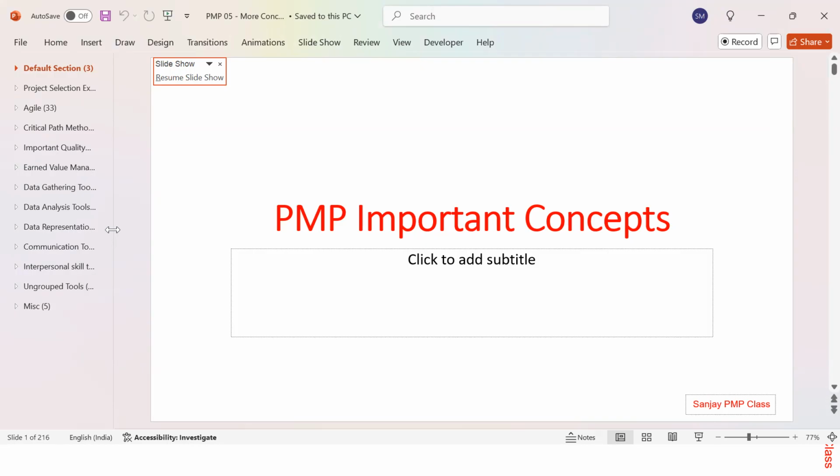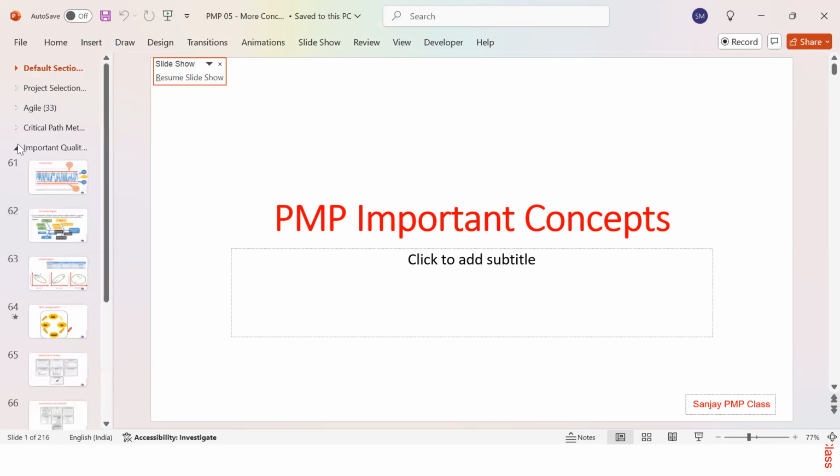And Ravi, which one is more stringent, control limits or specifications? Control limits are within the specification limits. Correct. They are more stringent, they are more tight. And what is the purpose? To control the outputs and to be within the specification limits.